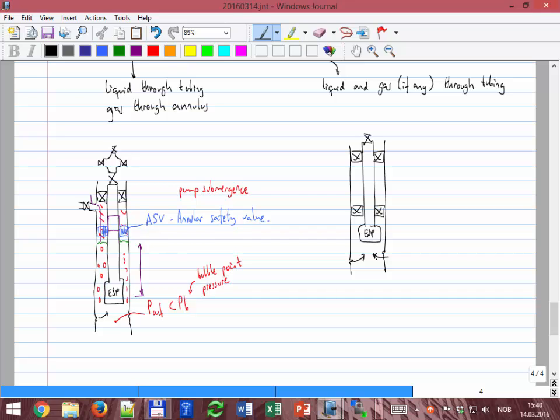Usually the presence of gas impacts very negatively the performance of the pump. If the pump was designed to achieve a certain head, for example 100 bar, when you have gas, it impacts very quickly. When you increase the amount of gas, this 100 bar goes very quickly down. It affects negatively the performance of the pump. You have more vibrations. The gas usually doesn't cool very efficiently the heat that the pump produces. The pump is producing heat, so that might also lead to more failures, etc.